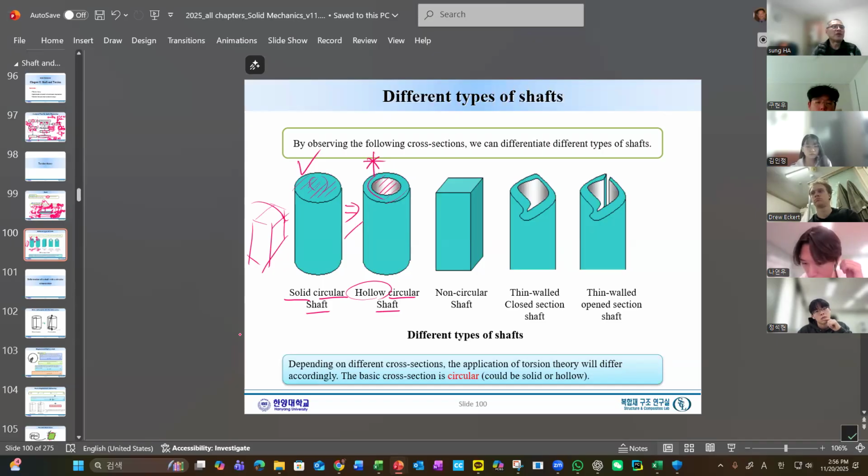So what do we do? We change to an H-beam or I-beam like this, and define the beam bending like this. Rather than this full solid, we move the area to the top and bottom, because the strain or stress is much bigger on the top and bottom sides. We do know the stress will increase like that.